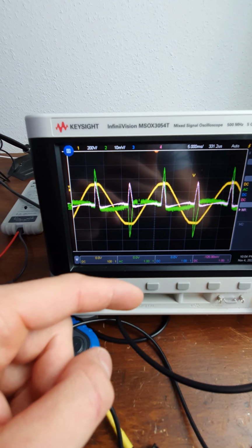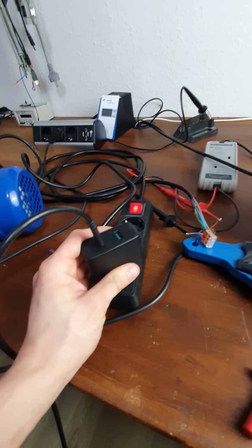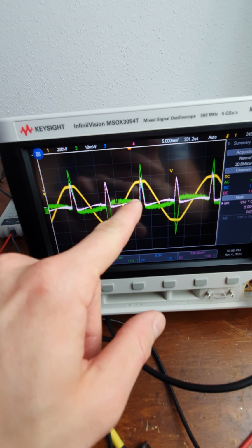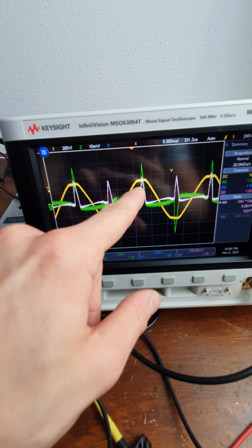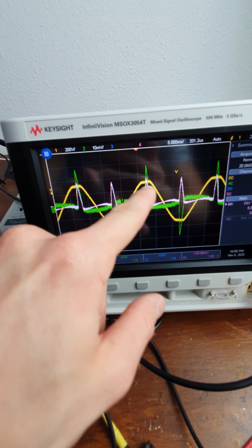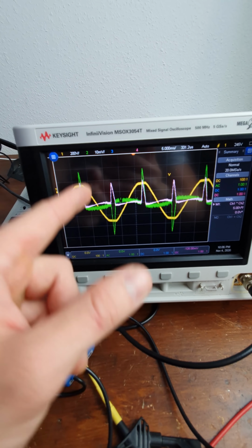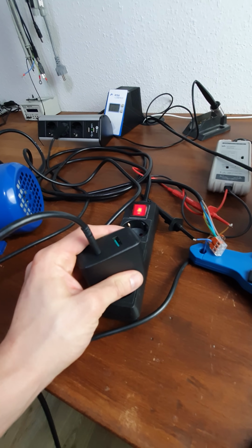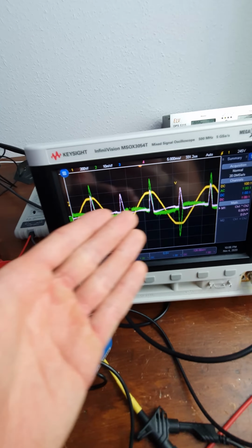That is also one of the reasons why nowadays in modern society, where we use lots of such switch mode power supplies, and they all draw a lot of current at the top, the sinusoidal voltage waveform is flattened at the top, because there's basically a bigger voltage drop, because that's the moment most of those modern power supplies draw their current.